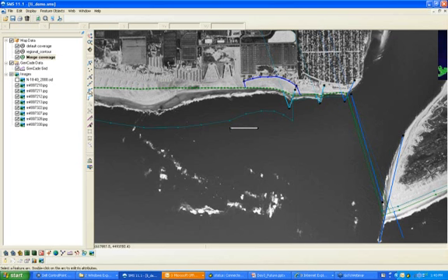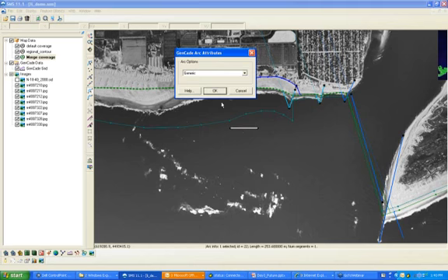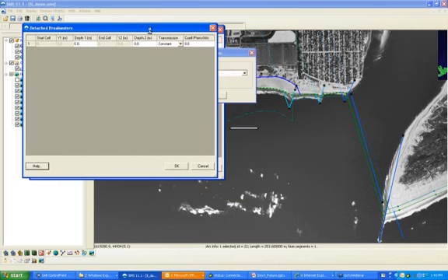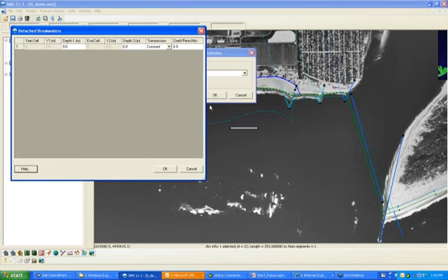So I'm going to go ahead and I'm going to click on Select Feature Arc, and I'll double click on the detached breakwater. Under Arc Options, now I'm going to name it Breakwater, and I'll go to Attributes. So the first thing that you'll see is we have our Depth 1 and our Depth 2. What this refers to is the depth at each of the tips.